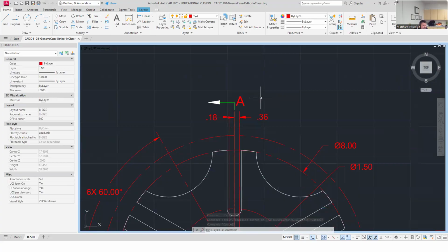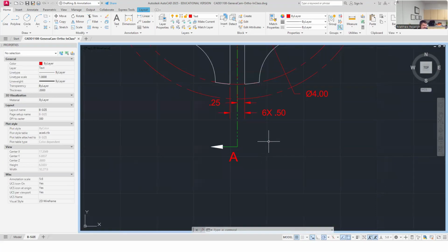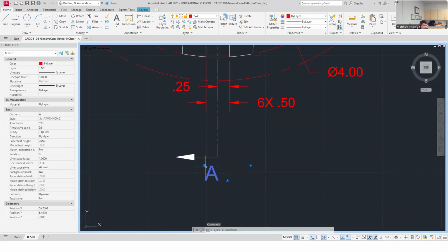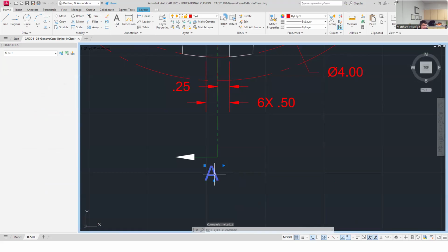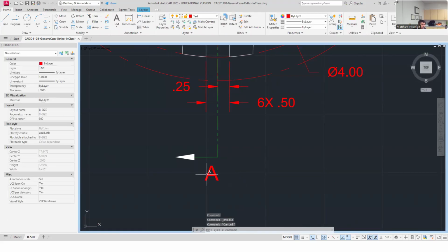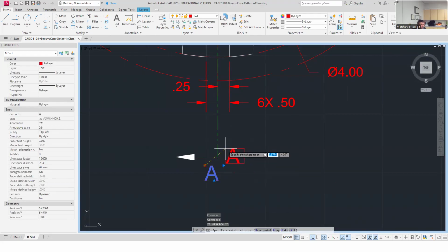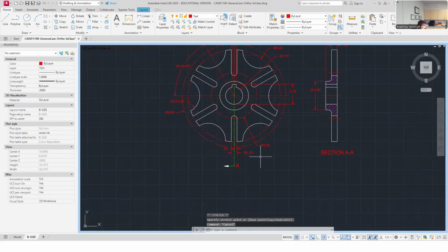Just somewhere close to the corner turn, put your section label. If I had another section, it'd be BB, CC. You try to keep track of that as the drafter of which one, like what's the alphabet you'd use next on your next section. Or sometimes detail views will carry. We'll talk about those later, though. I'm talking about them now. But in mechanical drafting, you mostly end up with some pretty simple regular views, I would say, and then you end up with a lot of detail and section views.